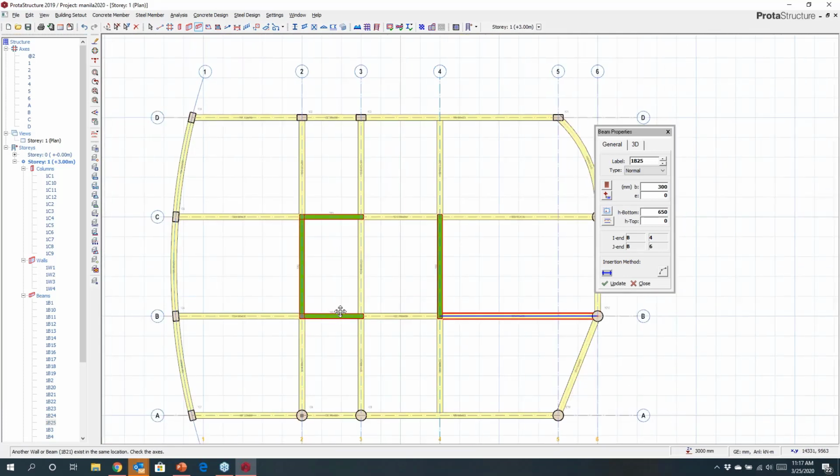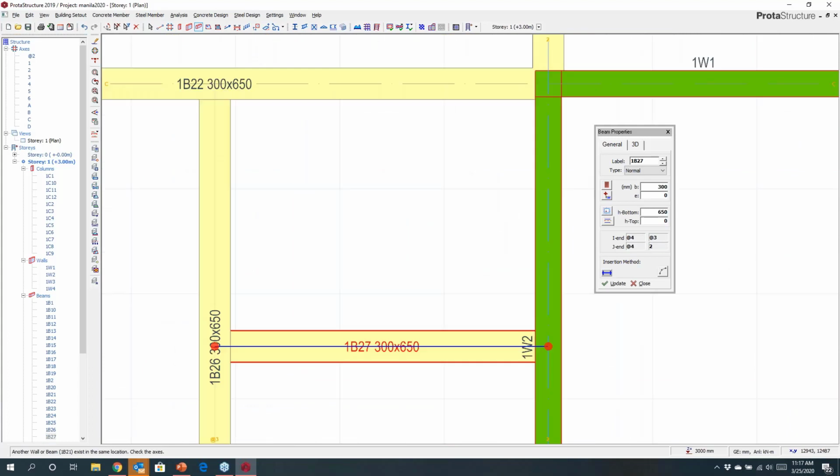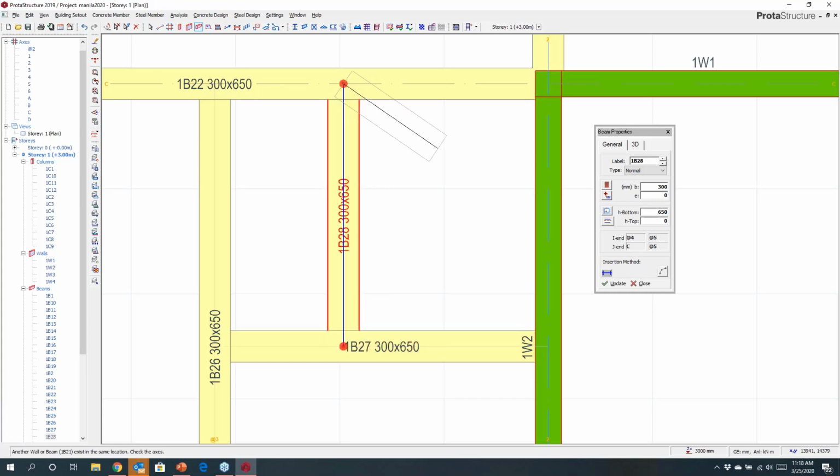So you can draw through. It's smart. It knows that they're there. There won't be any overlapping. And you can just use intelligent snap points to come in and create things quickly as you go. Now, if you have certain set out, if you hit F2, you can type in the exact coordinate that you wish to create, and then it'll pick up handy points like quarter point, mid-span, that perpendicular point, and you can create that element.